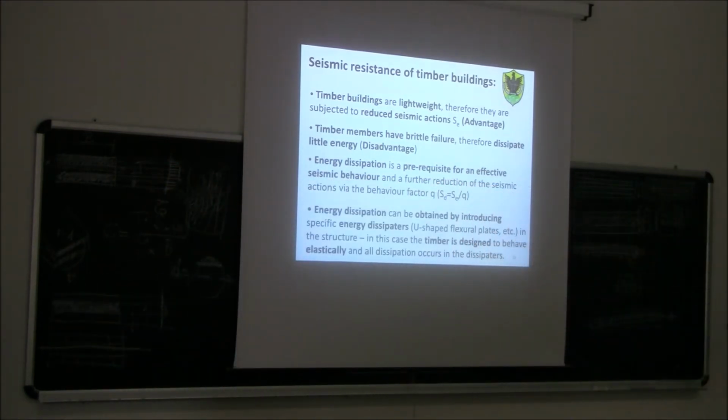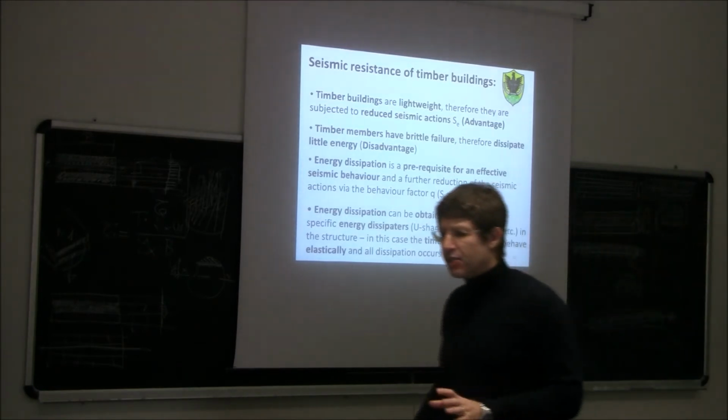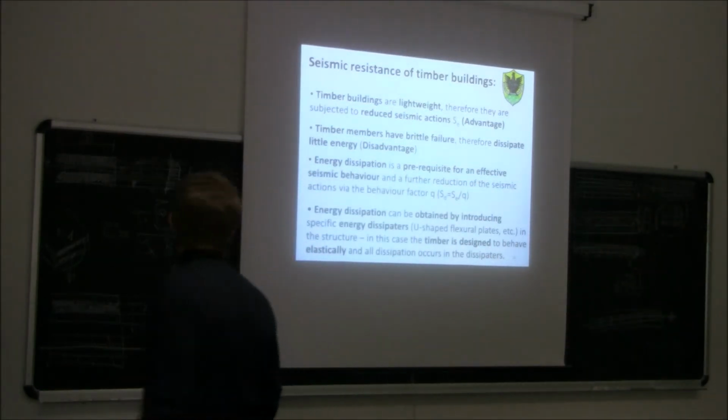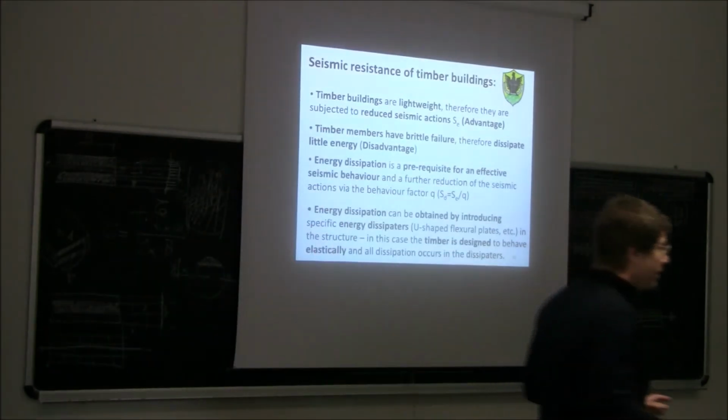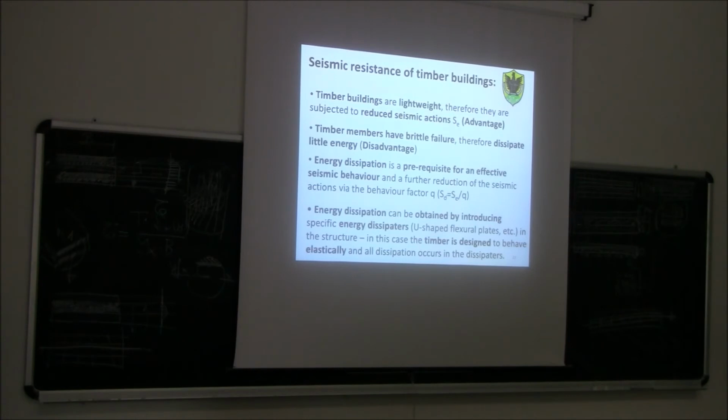Now, how can we obtain energy dissipation? We have also here two different philosophies. One possibility is to introduce in an elastically designed structure one or more energy dissipators. So we can say, okay, I design my timber structure and all the different timber members are designed elastically.